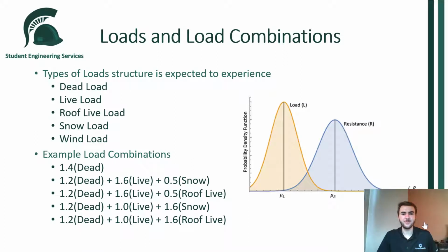Based on the general service of the building and the environment it is constructed in, each member will experience different loads or forces through the service life of the building, and these can be broken up into different categories, namely dead, live, roof live, snow, and wind loads. Earthquake loads are sometimes used in analysis, but based on the seismic activity and geography of this building, it was not